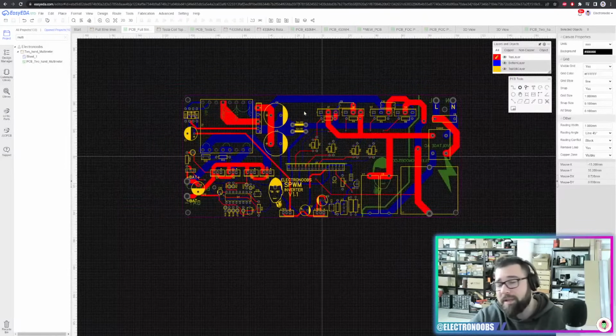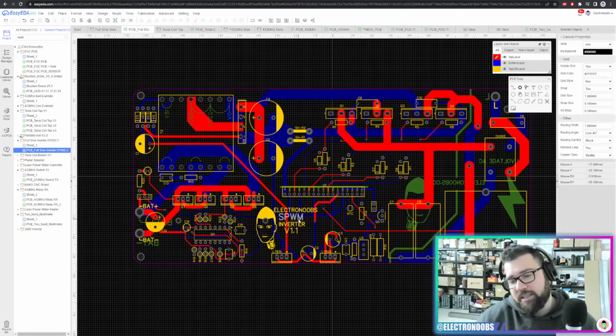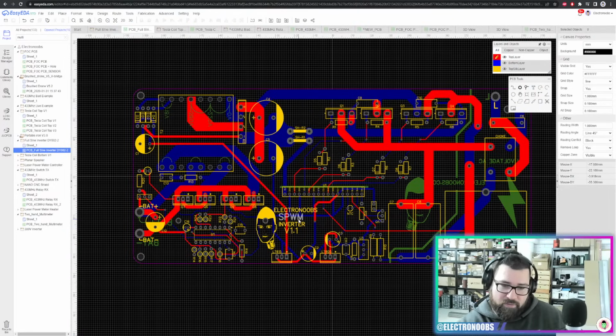So if you want to make a PCB for only one layer, because it's a lot cheaper, you can do that, but usually 2 layers is just $5. So it's your decision where to place the tracks. The idea is to get from this point to the other point with the least amount of work and the least length for the track. So basically that's how, in my case, I select on which side of the PCB to lay the tracks.